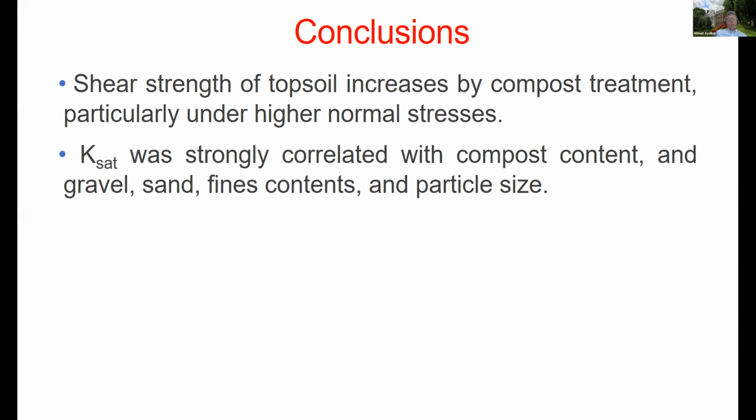K-saturated value was strongly correlated with compost content. I did not show you everything here. They could be found in the publication that I cited. And for instance, the gravel content, sand content, fines content, like particle size of the compost, obviously affected these saturated values. Again, we are using the term like gravel content here.